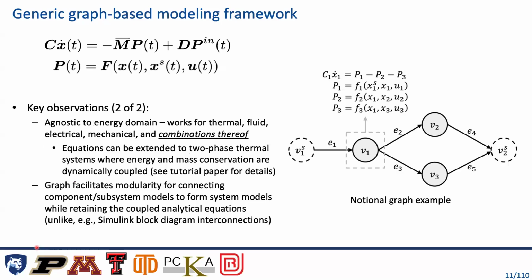Couple more observations here. So far I've just talked about conservation of energy. That could be conservation of thermal energy, mechanical energy, electrical energy, right? It could be more of those simultaneously. And it can even be applicable to two-phase systems. So when we originally derived this, we focused mostly on single-phase fluid systems. But you can do this for two-phase systems like refrigeration cycles, where you have a refrigerant that is transitioning from a gas to a liquid in two-phase state. There's a little more involved to do that than just these equations here, but there's a straightforward extension that is documented in the tutorial paper we wrote, as well as papers that are cited in that.